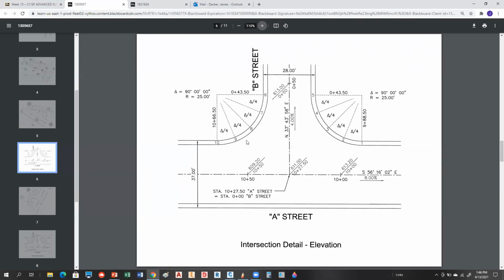I did this really quick. So if that center line location, station 10 plus 6650, I calculated as 1.32 feet below 609.2. Okay, so then you're taking that minus 609.2. Yes. So you're saying that the elevation of that point is 607.88? Yes. That would be the center line elevation, right? Yeah, but that wouldn't be the curb elevation.